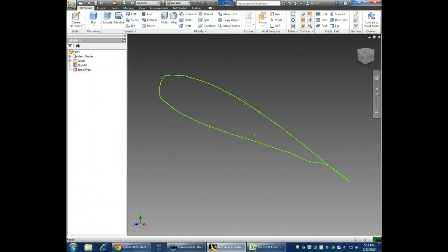All right. Once I get that fixed, what I'm going to do is I'm going to pick this and extrude it to a length of 4 inches and not more than 4 inches. That way my airfoil will fit in the wind tunnel and won't generate a lot of turbulence on the sides. Then you'll save that. We'll probably have a place for you to put that in Canvas so we can locate that, and you can turn that into me.